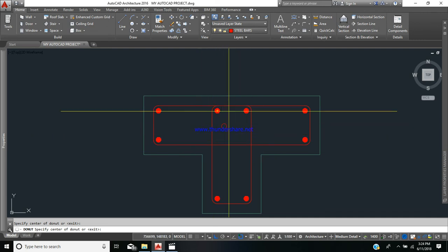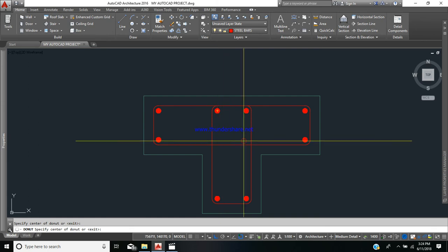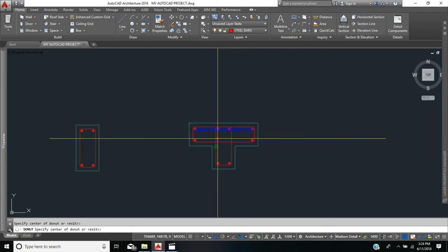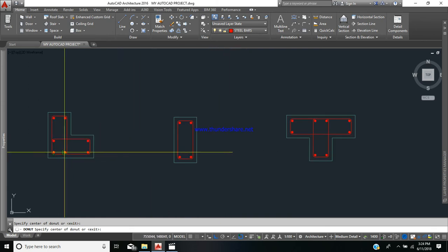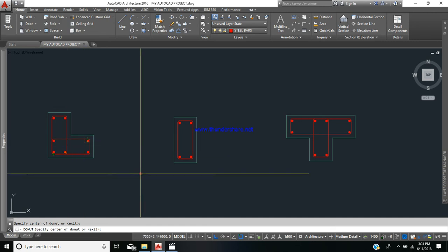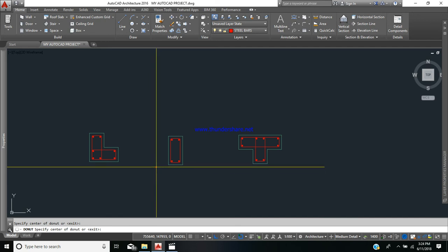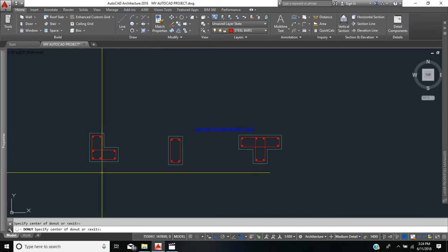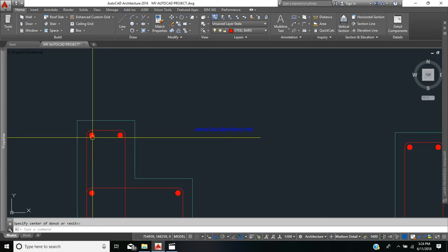There'll be no need to place stiffeners in these intersections. As a guide, we can be guided that only the corners that have been filleted would require the use of reinforcement. I'll give an escape to release the command because I'm finished installing my stiffeners.